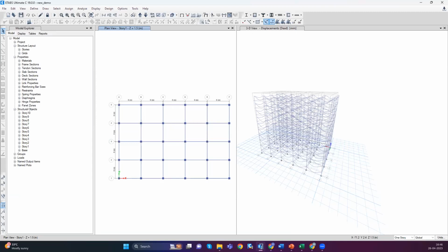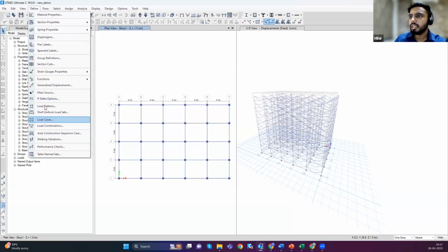The next question is related to the capacity curve. Let's say a capacity curve is showing some kind of brittle nature, but in order to make it ductile, how to do that? Whether we need to play with the reinforcement or change some sizes in order to obtain a proper ductile curve. I would say it is majorly dependent on the backbone curve that we are giving for the beams and the columns, for the beam specifically, because the hinges are formed in the beams. And if you see this backbone curve, just a minute.